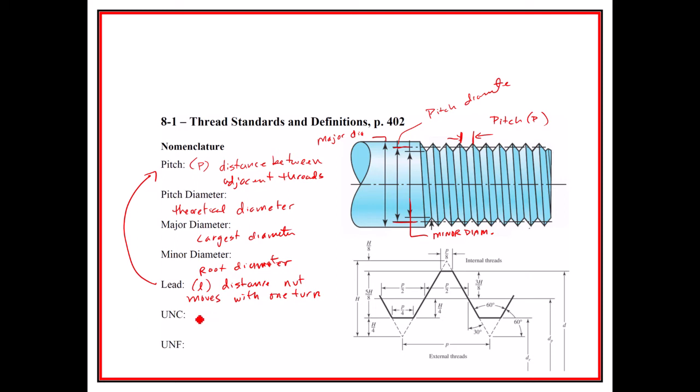And then we also have UNC. Okay, so this is the United States of America, and we have the Unified National Coarse. And I forget whether it's, yeah, that's that spelling, of course, right? And then you have UNF, which is Unified National Fine. But you also have extra fine and so forth. But these are the two big guys, UNC and UNF. And we'll see this right here.